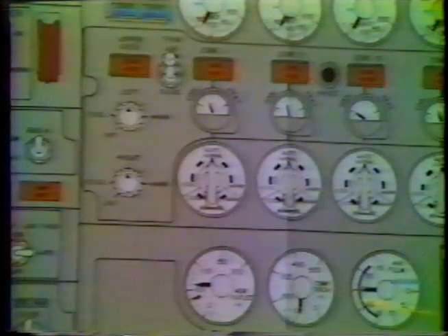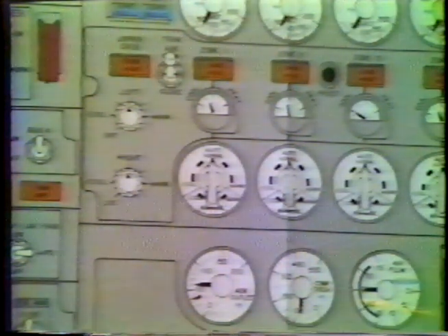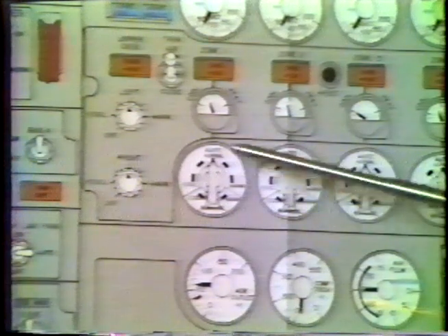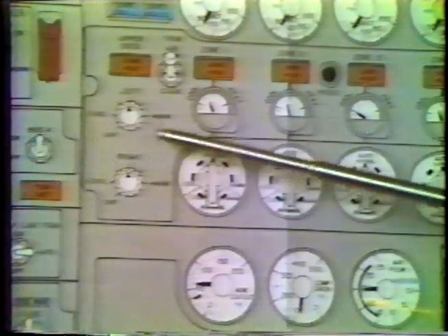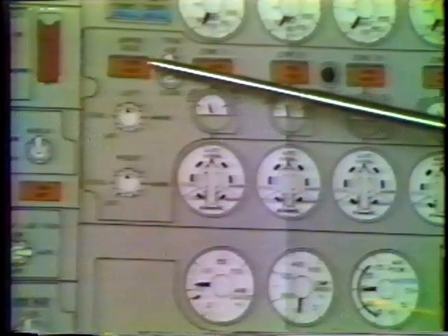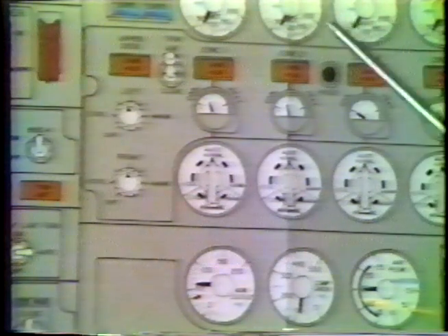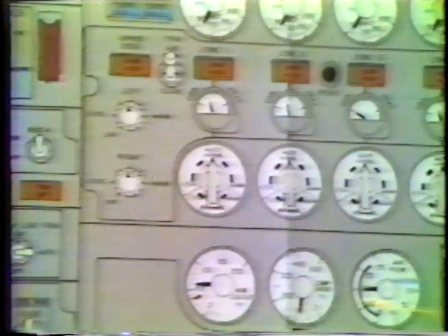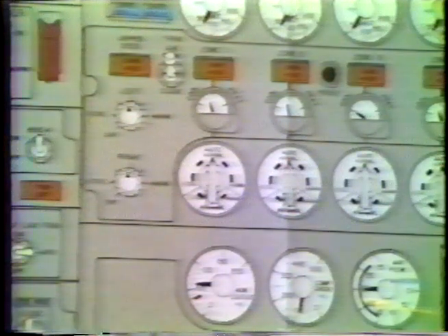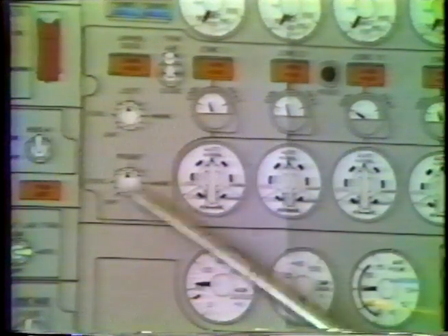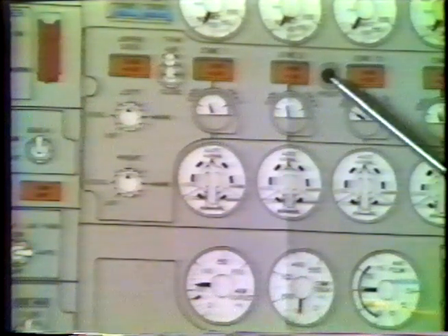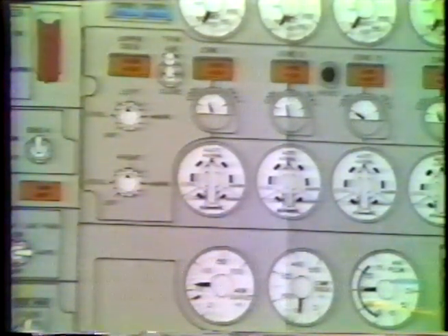Because generally, if you have 1 pack or no packs on, the airflow will be insufficient, the blanket heater will overheat, and you will get an upper deck overheat light. That light coming on means that section isn't working anymore. You can get rid of the light by turning the switches to off or pushing the reset button.